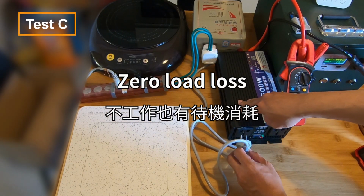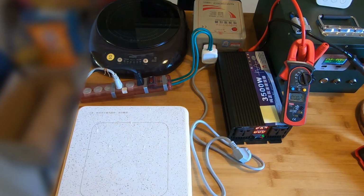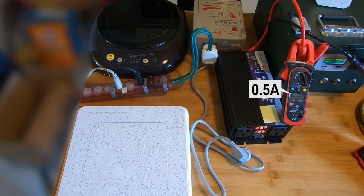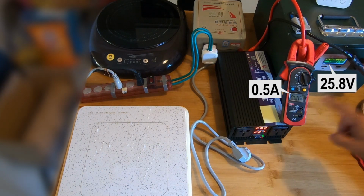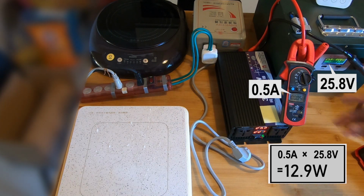Test C, zero load loss. After turning on the inverter, you can see that the current is raised to 0.5 amp on the ammeter. The battery voltage is 25.8 volt. The input wattage of the inverter is about 12.9 watt. This means that when the inverter is turned on, it will continue to consume battery power even if it is not connected to a load.